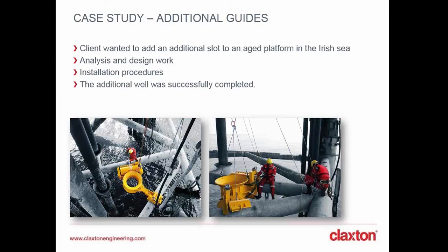As well as that, we prepared project-specific installation procedures, also for the installation via rope access. The guide was lifted over the side of the platform, then slung into place within the jacket structure and firmly secured within a few hours by a crew of 4 abseilers.